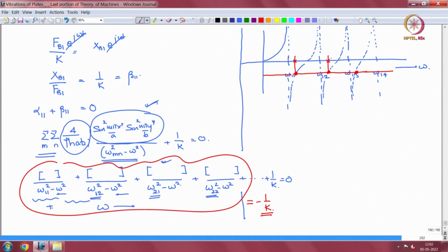You can also see that every resonance is raised, or every natural frequency increased. Why? Because we stiffened the shell or the plate, the stiffening effect of the spring.